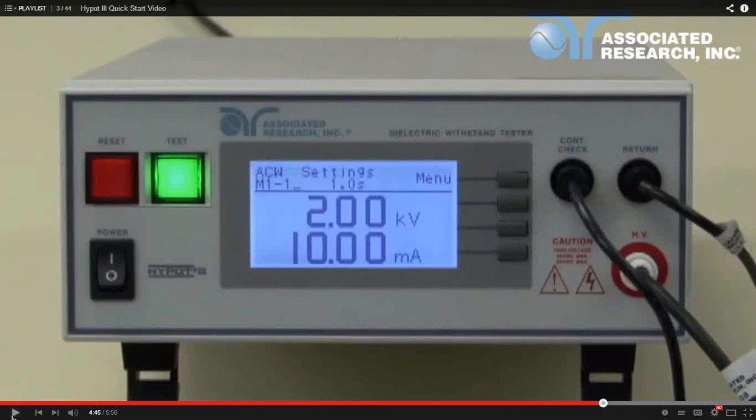What I'm showing you here is you saw I plugged in a continuity check lead, and what that is looking for is continuity between the cont check and the return port. So again, you would apply the cont check lead to the ground pin and the return on the chassis, and as you can see, the light went on green. Now, fortunately on our units, you can set a high limit value for resistance. It goes up to about 1.5 ohms. But again, as long as it's under the 1.5 ohms, the light's going to go on.